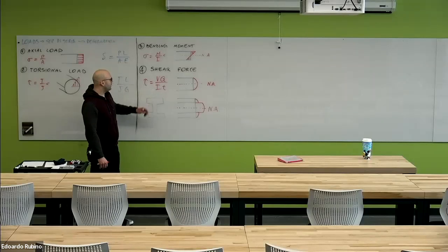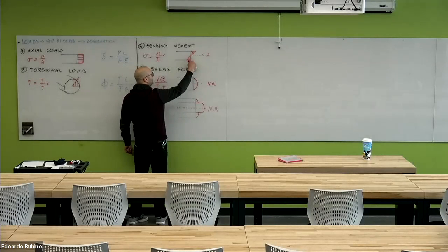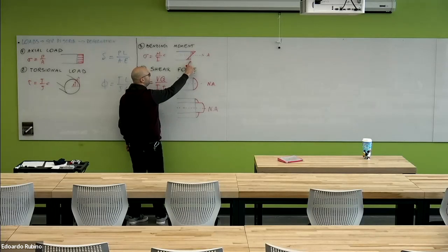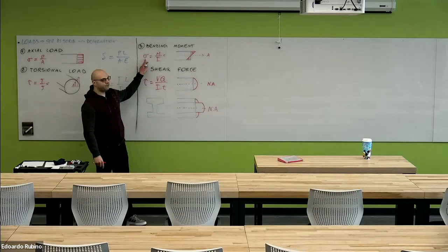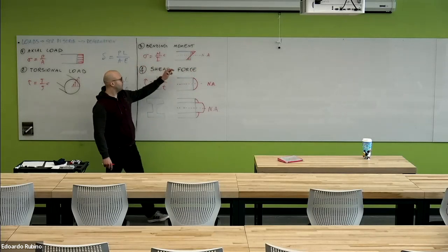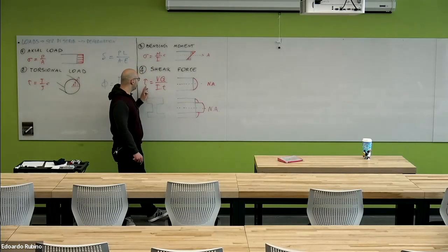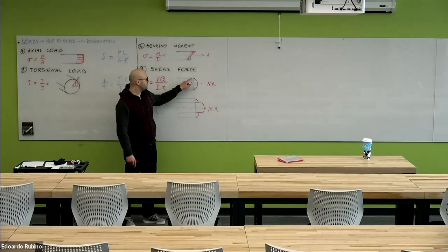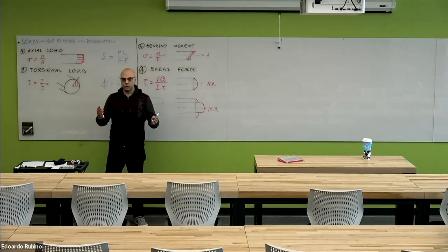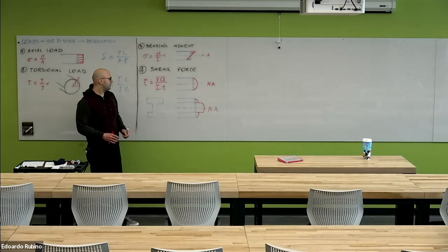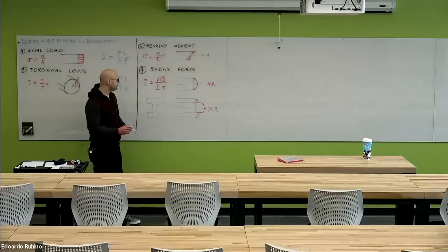If we look at the top and the bottom edge of the beam, from the flexure formula, the stress is actually maximum. If we look at the shear formula, the stress is actually 0 at the top edge and the bottom edge. So these two equations give us a kind of opposite result, especially when we want to identify where the maximum stress is.